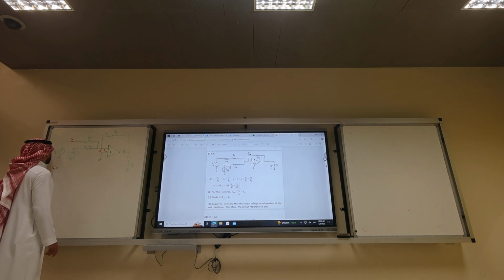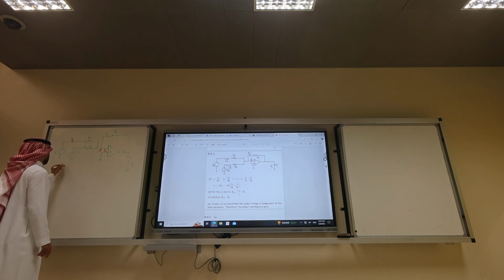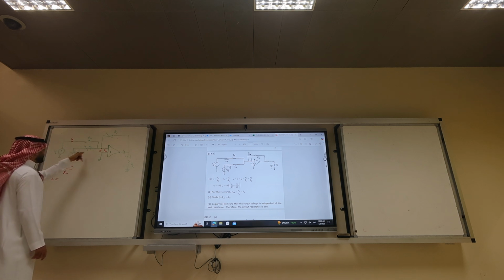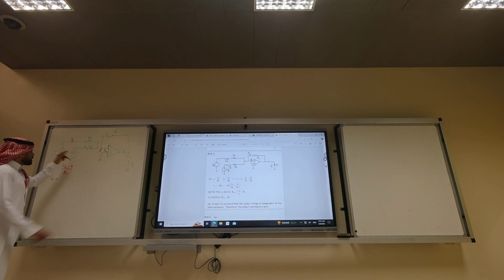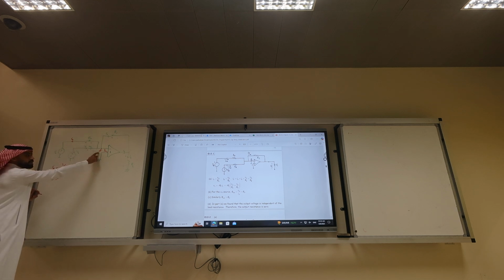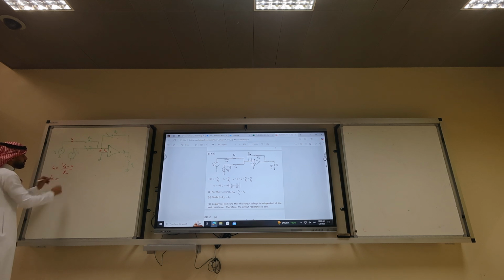IA is V input minus 0, or VA minus 0 over RA. IB equals VB minus 0, okay? This is VB, this is a virtual 0. So VB minus virtual 0 over RB.